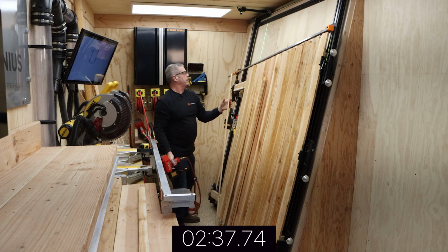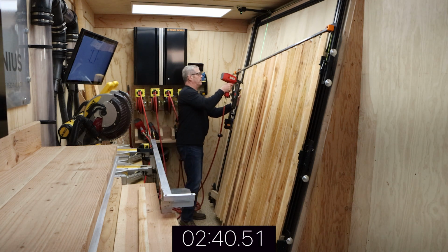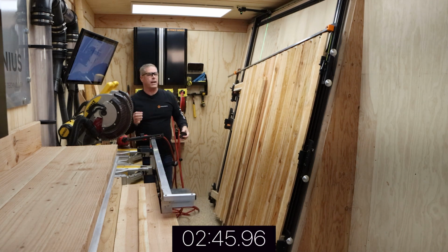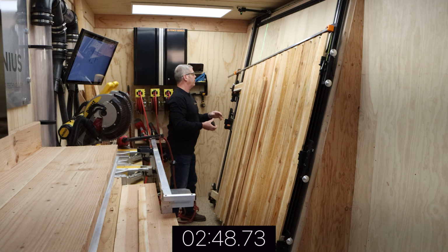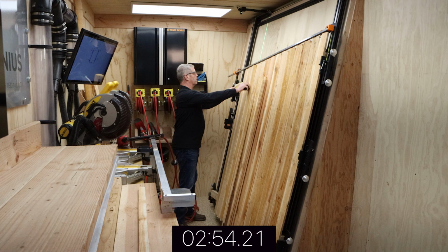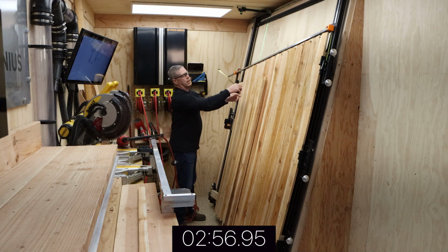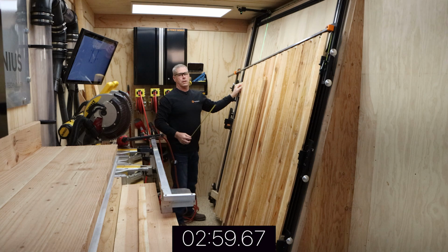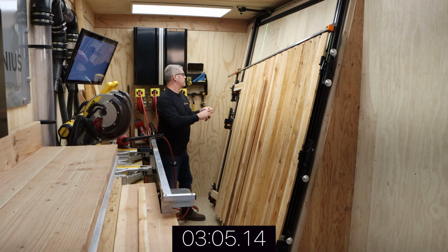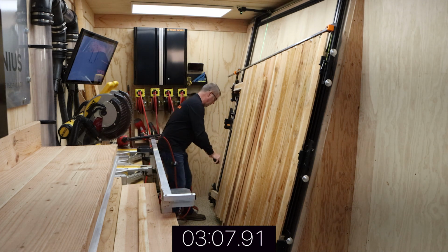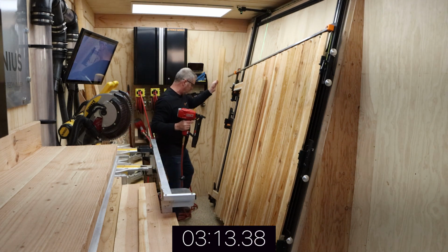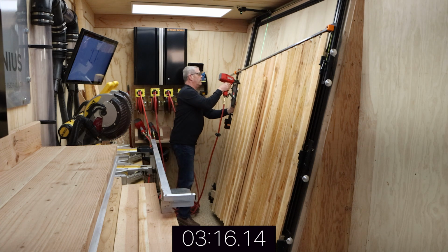Okay, so I get to my laser here, and this laser is set to my 5.5, so I'll know what my end reveal is. I'm also able to simply measure 16, and I can tell based on this that I don't have a super narrow rip at the end. I can also tell based on this how far out of plumb I am. So I'm actually nice and straight, so I really don't have to do anything. I can just roll right on in.